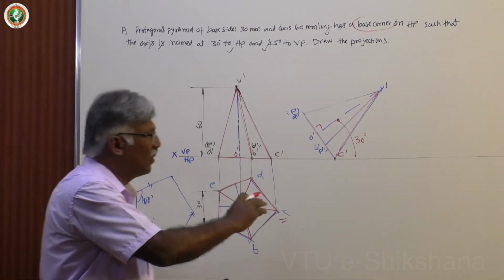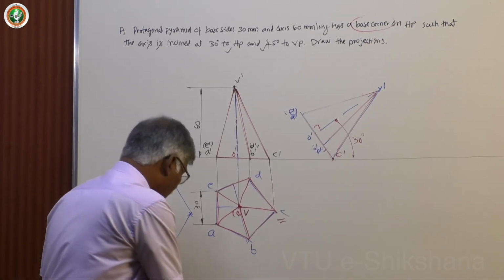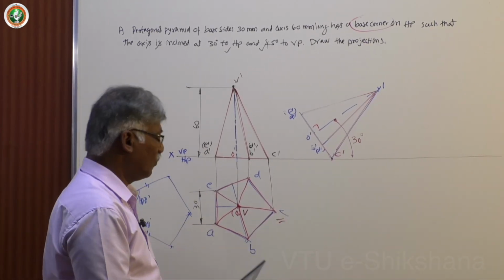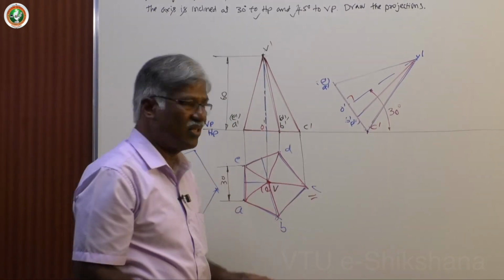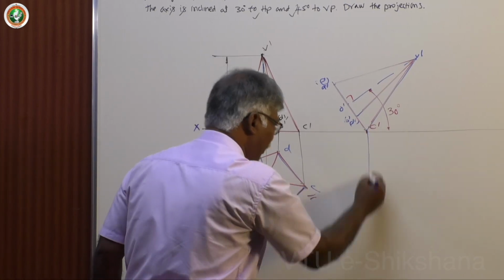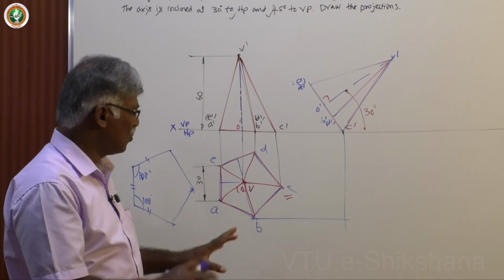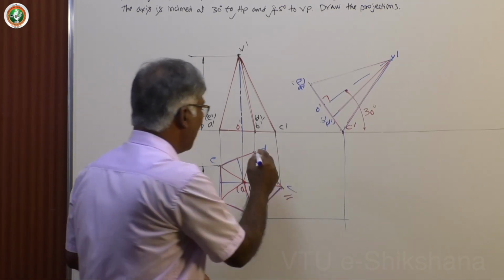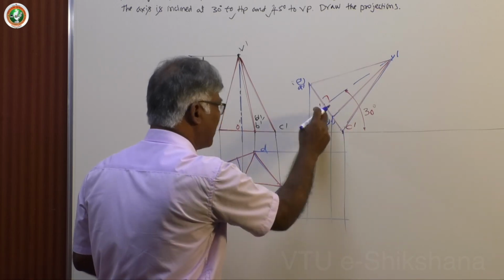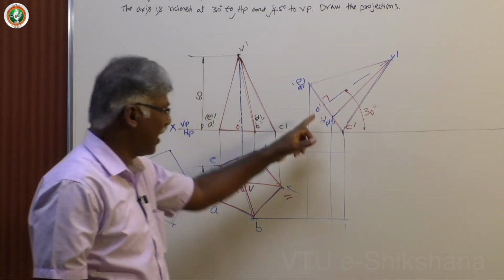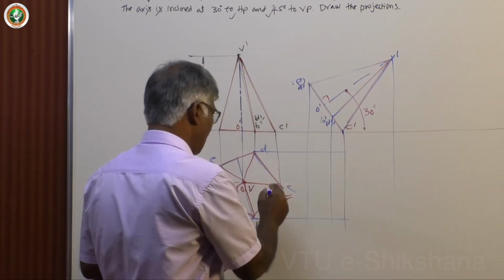So, after you clarify this condition, then go ahead with the second figure top view. How to draw the second figure top view? So, first you keep the base only, do not draw all these projections up to V, draw only this topper, say using alignment indicator into computer, whatever the points you want, only that one you fix. Otherwise, manually also you can optimize your work by projecting only this, but do not project axis. This is most dangerous line. I will tell you why. Then V.